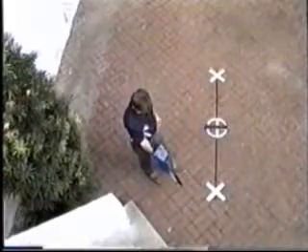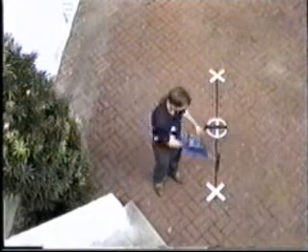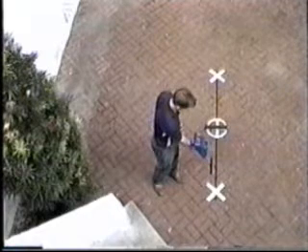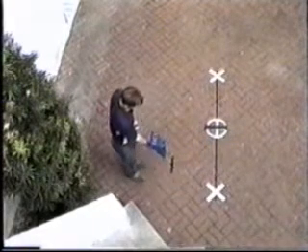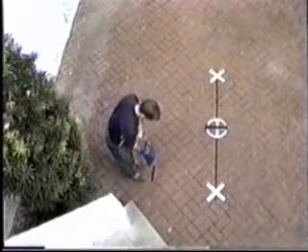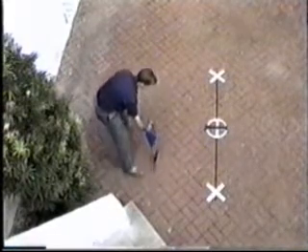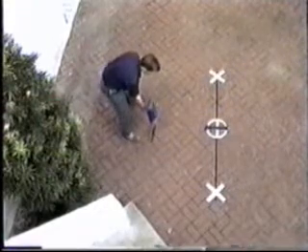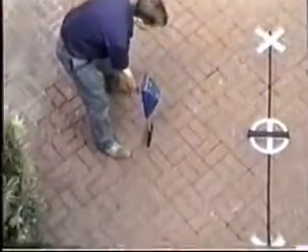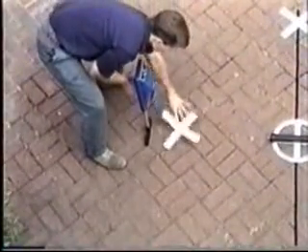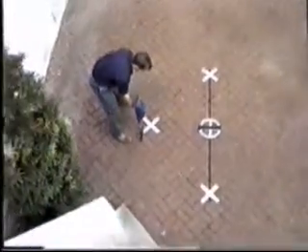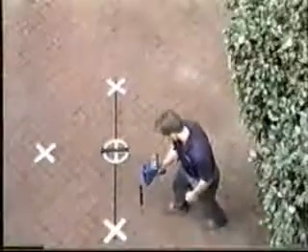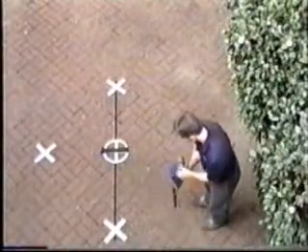To locate the end nulls, place the detection antenna in the horizontal position, forming a T. Hold the antenna parallel to line A and back away several feet. Again, turn the gain up on the receiver. Now, holding the receiver in this orientation, walk parallel to line A until a signal null occurs. Mark this spot. It is the first end null. To find the other end null, repeat this procedure on the other side of line A.